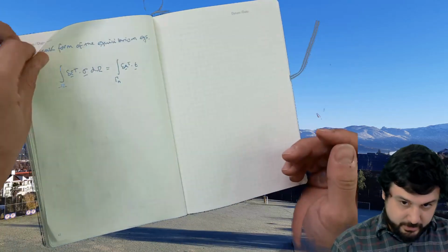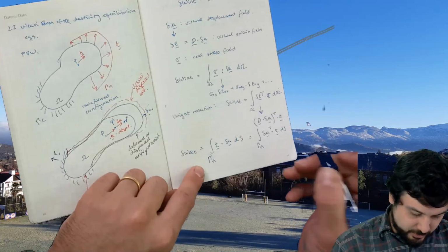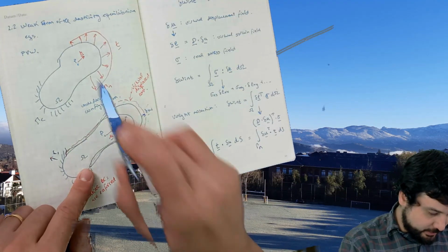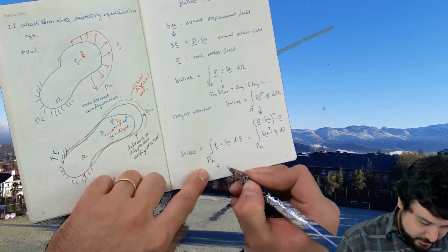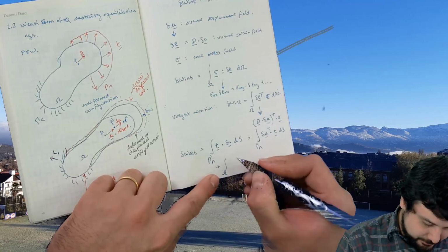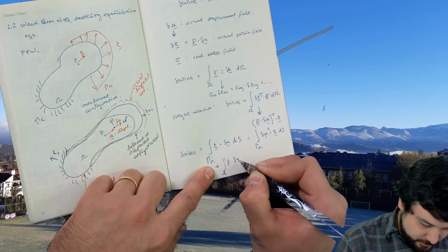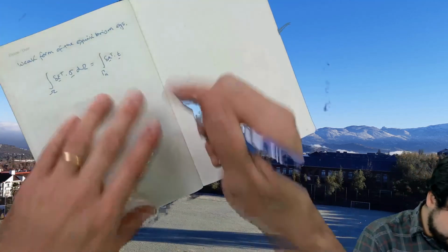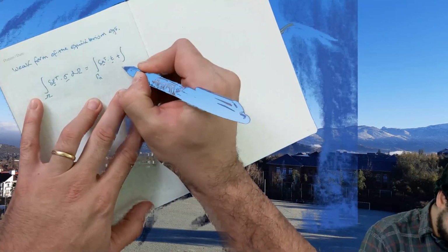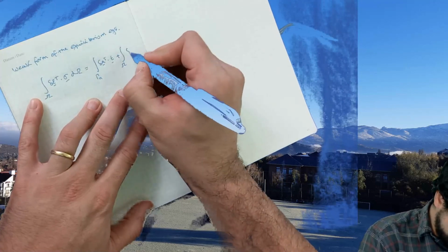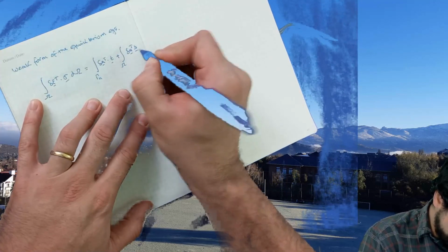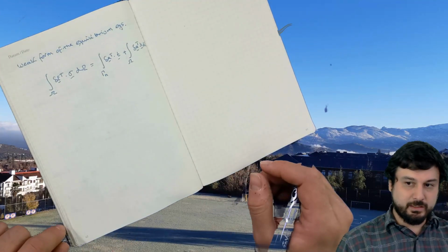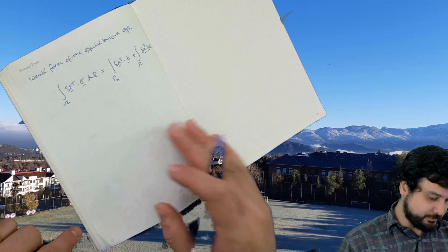And I missed something. Over here in the external forces, the other thing that does do external work is the body forces. So we add a term, integral over omega, delta U transpose b d omega. And that's the weak statement of the differential equation.